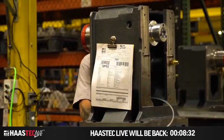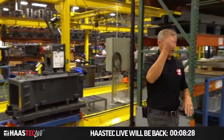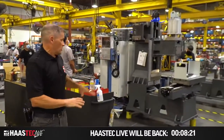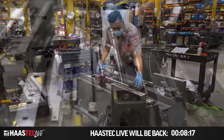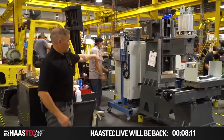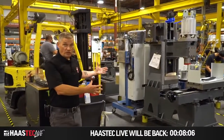You can see that this is kitted, ready to go, so that once it's assembled here, it's taken over to this side. This is where we do the entire stacked axis method we were talking about earlier. We place the base on the ground, add the linear guides and ball screws, install the saddle and table, and then we take that column assembly that we built over here, lift it with a crane, drop it onto the top of this guy here, and you essentially have the bare bones of the machine.